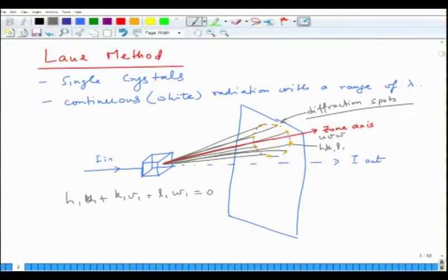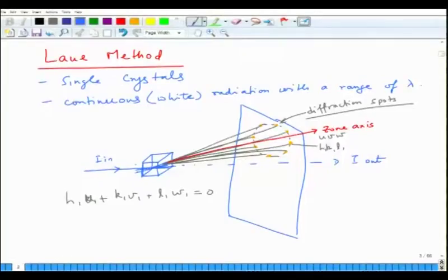So what basically it means is that you will have a zone, you will form a cone, and this is the transmitted beam. Typically the angle, and we know that the angle between, so for most of these the plane orientation would be, so if you combine these two lines, some plane would be like that, some plane would be like this. If you combine this line, some plane would be like this. The planes will have different orientation, but not all planes, only those planes which have appropriate interplanar spacing and angle satisfying the Bragg's law. That is why we use variable lambda.